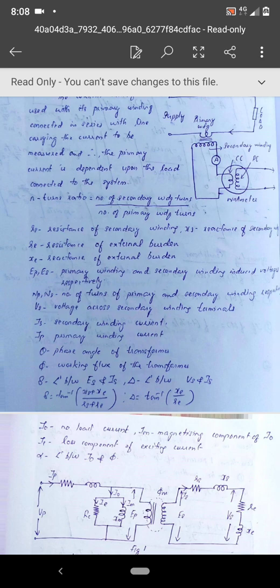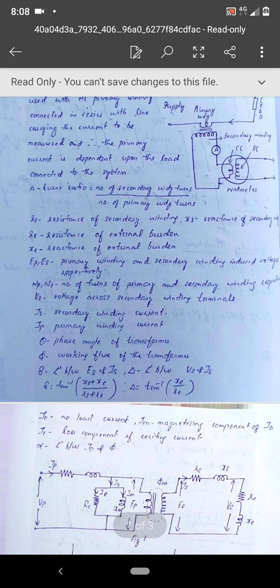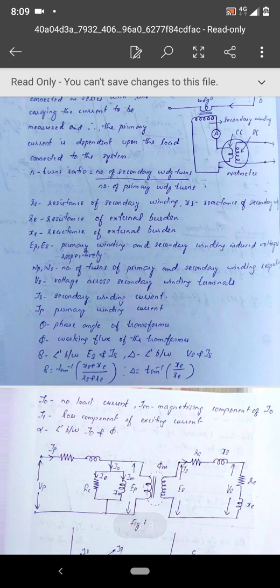So a current transformer is actually a step up transformer. That is, when you step up the voltage, you step down the current. That is what you require. So here also, when the conductor is having only one turn, when the primary is the conductor itself, then if you have a few more turns in the secondary, that becomes a step up transformer.